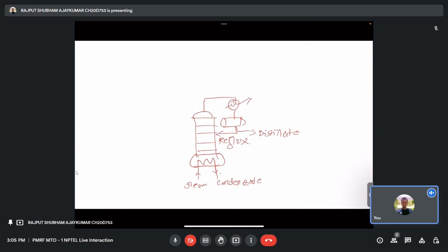In the case of multi-stage batch distillation at constant distillate concentration, the reflux ratio is not constant. Alternatively, the reflux ratio is continuously increased so that the product concentration remains constant for some time. This is called variable reflux. If the distillate concentration is fixed, the reflux ratio varies. Another term is the variable reflux operation. So there are two types of reflux we talk about.